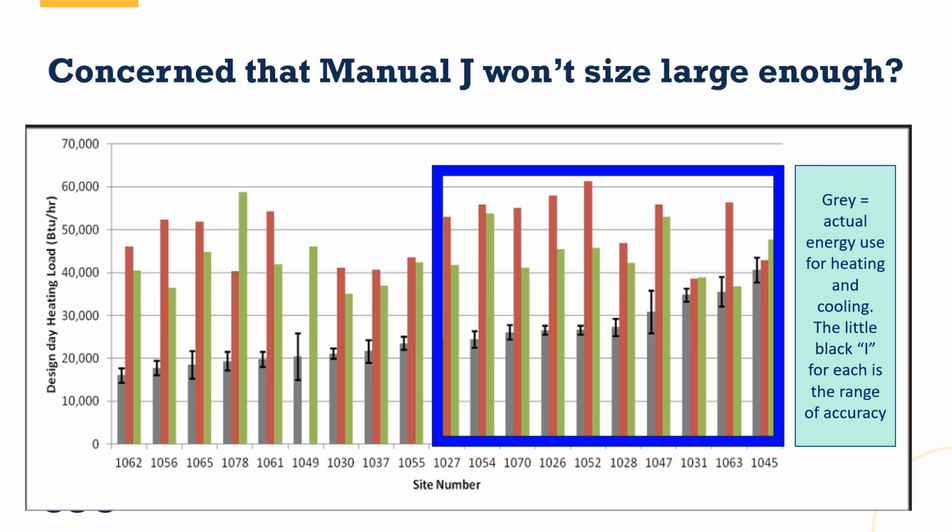Telling me a couple of things. Contractor A and contractor B could have been using slightly different software. They could have been using different standard inputs. So in other words, they could have said, well, we didn't do a blower door test, so one of them may assume that the homes are average in their leakiness. The other person may assume that they're somewhat leaky as a standard. Those kind of things, which we did not have the ability to check, must be happening because we're getting these different numbers. And we are getting much higher numbers modeled than we were measured.